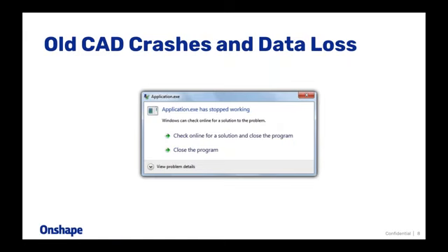But even if you have autosave on, the issue with that is that every time it autosaves, it's going to save over the previous autosave. So, if you're working away and somebody's made a mistake or you deleted something, and then it autosaves and then it crashes, you've suddenly lost all those changes because you haven't got an undo anymore, and the autosave saved it after you deleted a bunch of things. So you have to be a little bit more careful with that.